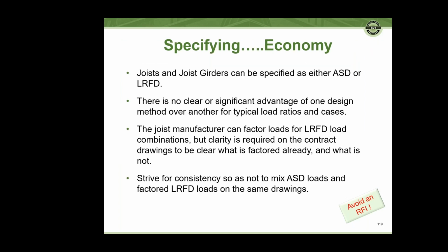A couple of notes here about ASD or LRFD. Joists and joist girders can be specified under either design method. There's no clear or significant advantage of one design method over another for typical load ratios and cases. Depending on the ratio of dead load to live load or how much wind there is, there could be some very, very slight differences, but they're really not significant.